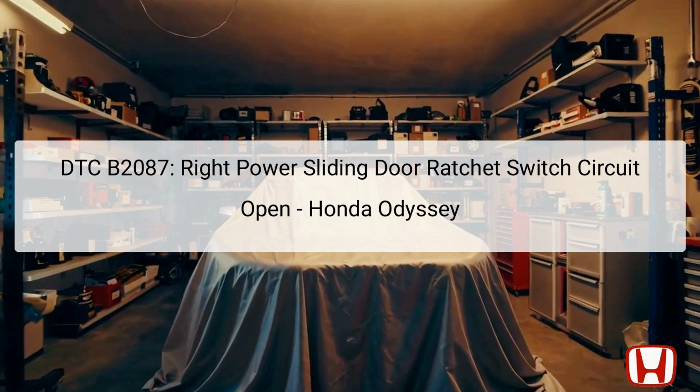It's crucial to understand that the power sliding door ratchet switch plays an essential role in the vehicle's automatic door operation system. Located in the right sliding door, this switch facilitates the door's opening and closing functions through an electrical signal to the power sliding door control unit. If this circuit experiences an open condition, it can lead to door malfunction, rendering it either unresponsive or inoperable. This guide will provide a structured troubleshooting approach to help identify and resolve the issue effectively.